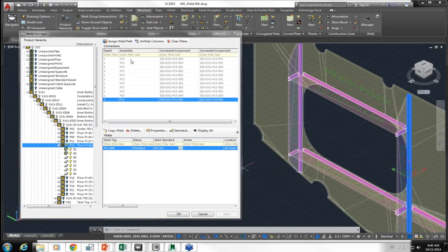I'm just looking at one of the questions, and one of the questions is, are weld dimensions, the leg length, the fillet size, etc., also visualized? Dan, no, they're not. What we're looking at here is a generic visualization of the weld, so we're not taking into account the shape or any of those types of things. One of the options in the drawing options for weld allows you to specify the diameter of the weld, but currently it's just a generic cylinder essentially used to represent the weld. And yes, you're welcome, Dan.